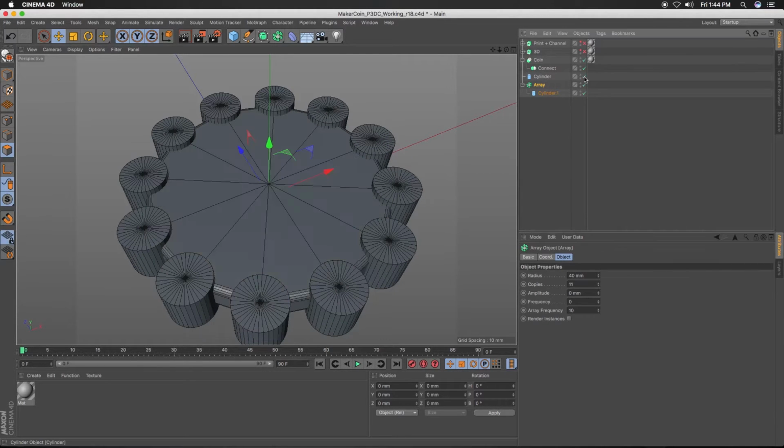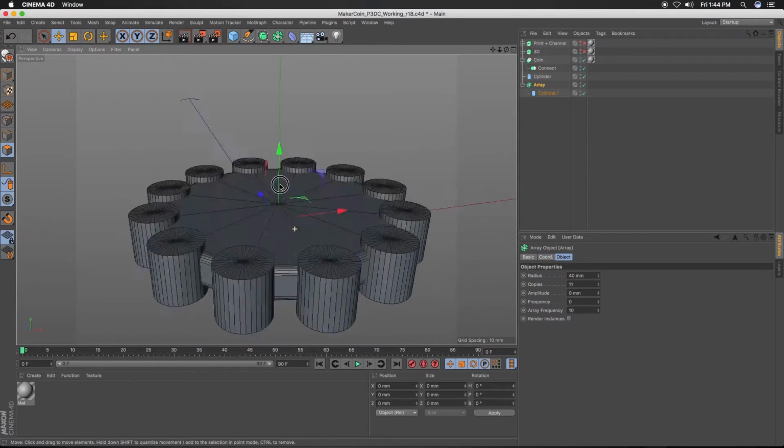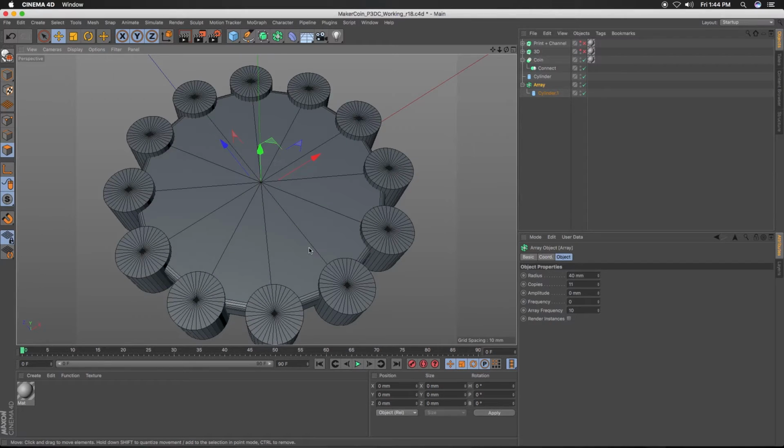If we turn on our cylinder object, I wanted these to all land right on the turn here, right where the polygons end and it makes its next section. So there'd be flat edges here, and we'd have some nice rounding, plus we have our bevel going on. And the bevel is on both sides. Here, I'll show you. The bevel is actually on both sides. So this will make it easier to get up off the print bed, and it gives it a little more unique flair.